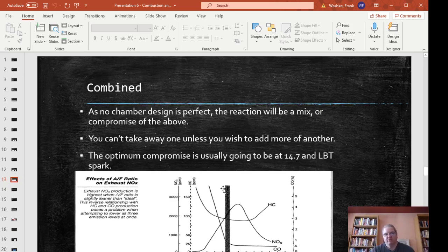It's not 100% stoichiometric. It's not 100% rich or lean. You just do the best you can, and then you deal with whatever's on the other side through aftertreatment. So the typical engine going out of the exhaust is really well done. If you add in the aftertreatment that we do, by the time you get to the tailpipe, there's virtually no emissions at all whatsoever.